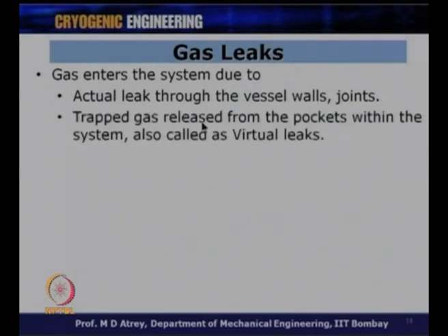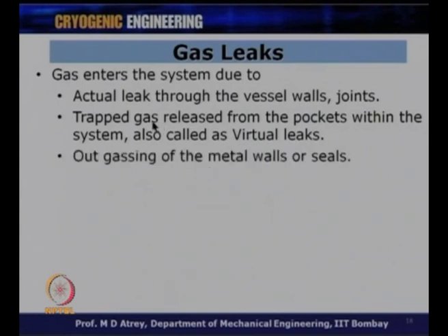Then the trapped gas release from pockets within the system, also called virtual leaks. So, there is a material surface, and there are some trapped gases inside this material. It will get released once you start vacuuming. That also has to be estimated. See, this parameter becomes very important if you want to go down to 10^-8, 10^-9 kind of vacuums. All right. So, these are very important to be considered while calculating pump down time.